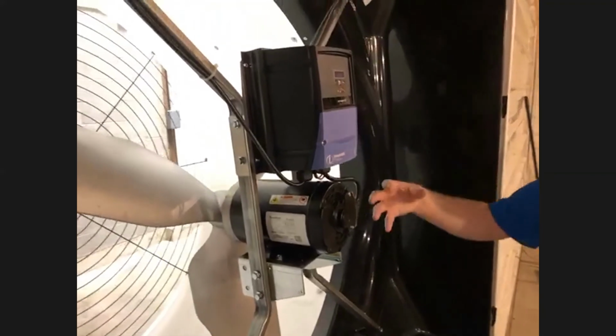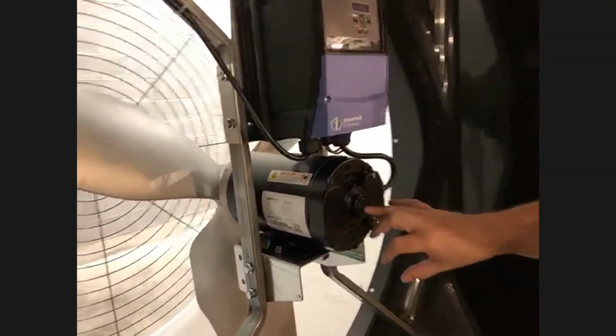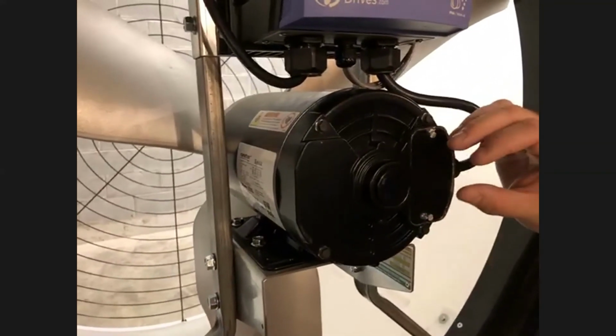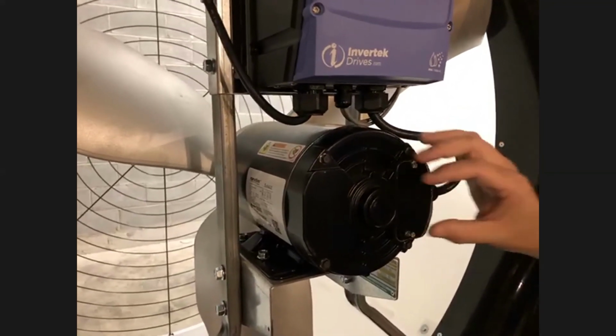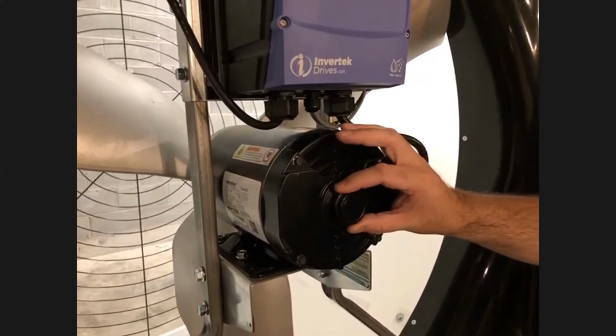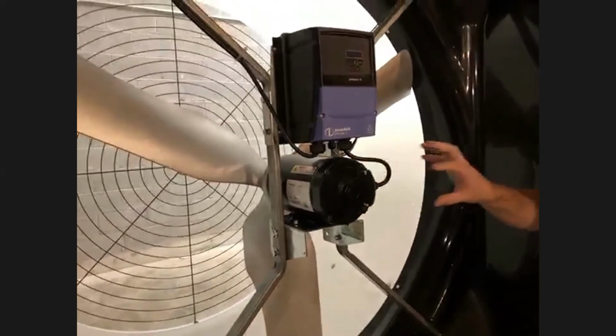And with the direct drive, with the motor itself, you actually have a larger shaft than normally. Given that larger shaft, it gives more stability, more robustness to the design, and also gives larger bearings, which are also stronger for the fan themselves, for the motor. So that's a big plus there. Everything is more robust.